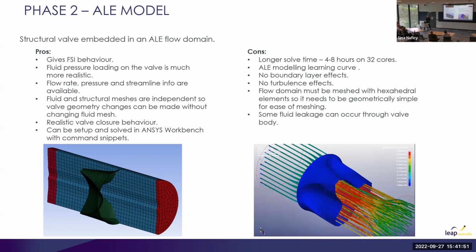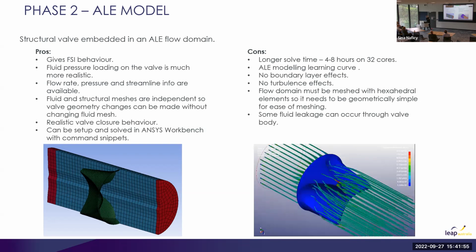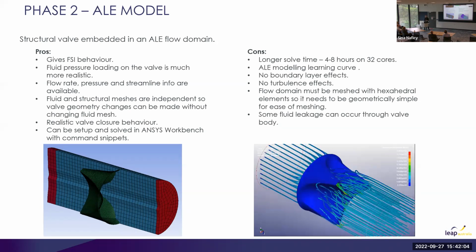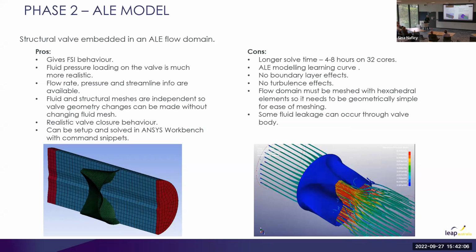You can get realistic valve closure behavior, and we've managed to set this up in ANSYS Workbench using a whole bunch of command snippets. So the workflow is very efficient. So we've automated a lot of that process. On its own, ANSYS Workbench can't do the simulation, but you can do a lot of trickery with command snippets and name selections and stuff to get it to do what we want.